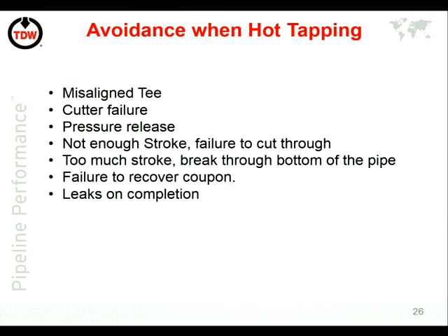We also have to make sure that we don't have too much stroke. There's only one thing worse than having one hole in a pipeline, and that's having two holes in a pipeline, with a hole in the bottom. It's just not recoverable once you do that. You will actually release, there's no means of containing the pressure. So that is one of the key things when we do any hot tap operation: you do not go through the bottom of the pipe.